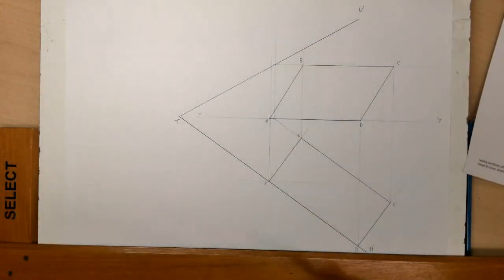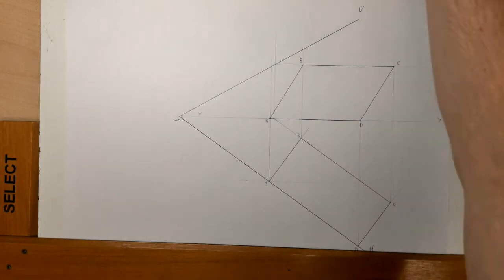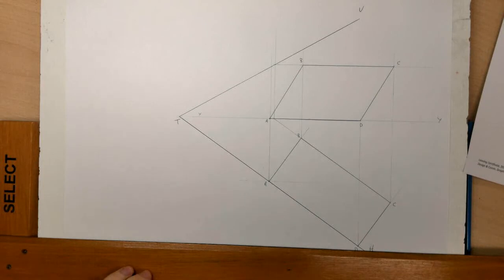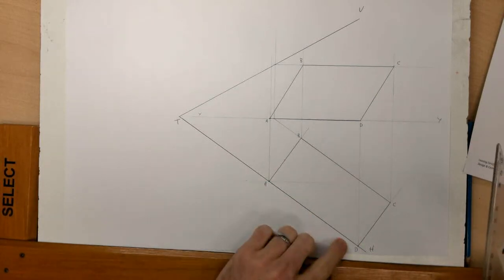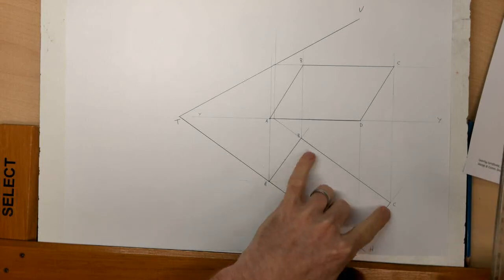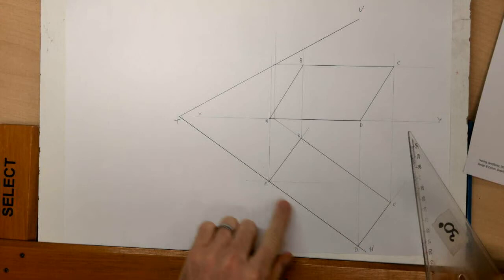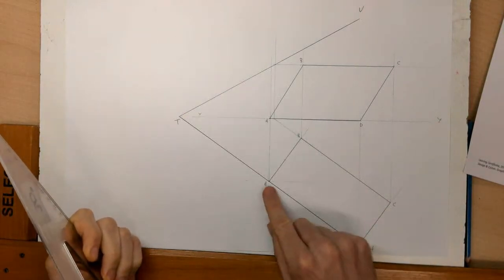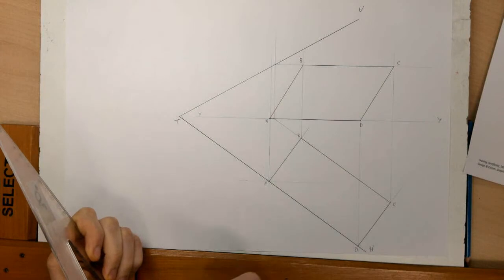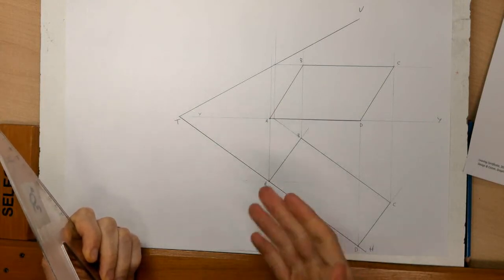Okay, there's a couple of different ways of finding the true shape of it, but we'll start with getting the edge view. So line AD, okay, is a true length line, same with BC. So if we actually look out along that line, so looking out here, okay, we'll get a point view of AD, and if we have a point view of a line that's contained on a plane, we get an edge view of that plane.